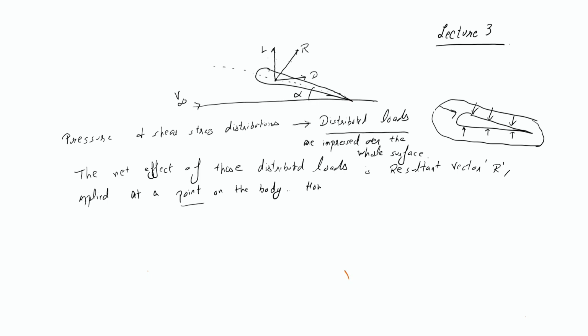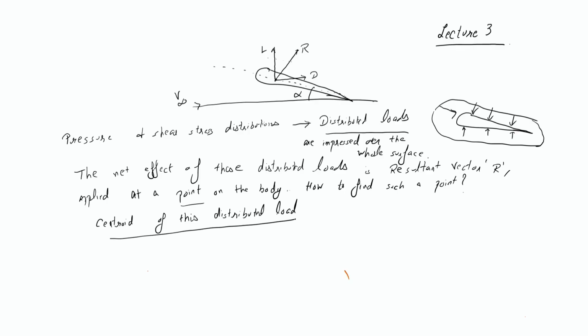Now, how to find such a point? This also we have discussed. You can find this point by using the centroid of this distributed load. You just have to find the centroid of this distributed load, that is from integral calculus. Then you will get a point. That point is nothing but the center of pressure, CP.